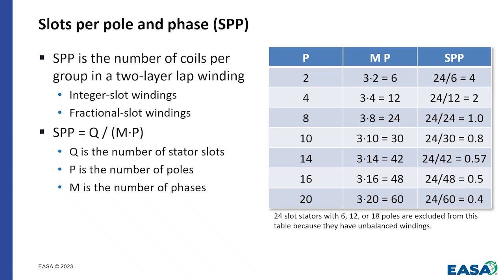But below that number, you're going to look at the number of slots, and you're going to look at the number of poles, and you're going to say, I can't make a winding to work. If I need 30 groups of coils and I only have 24 slots, there's no way to achieve that. And that's where these windings, and the way the theory works behind them, gets a little bit unusual for winders that are accustomed to working with visually symmetrical objects that make sense.